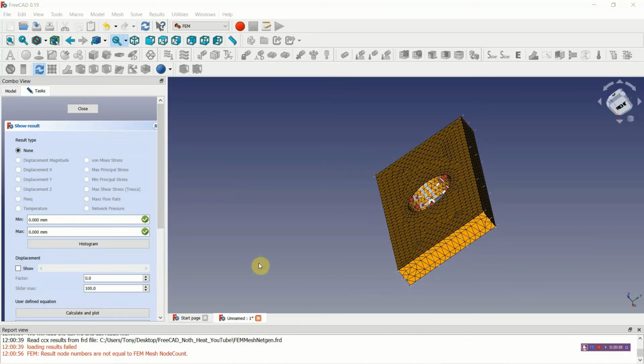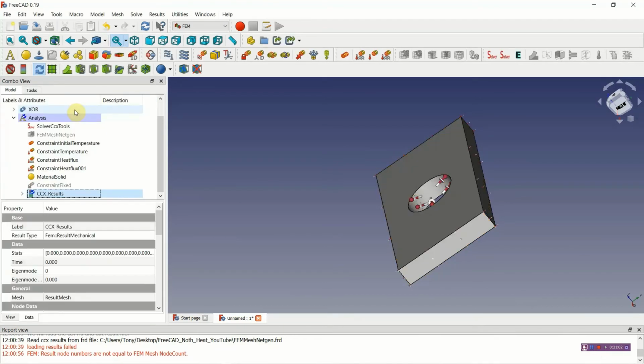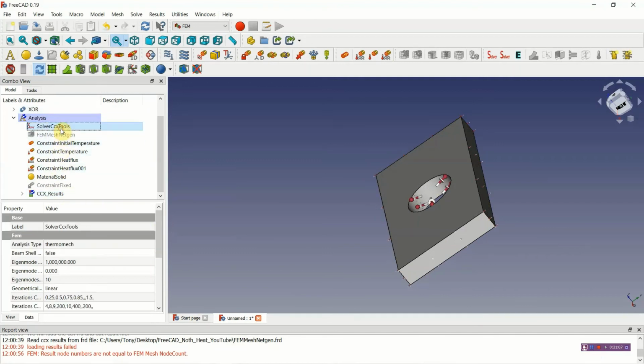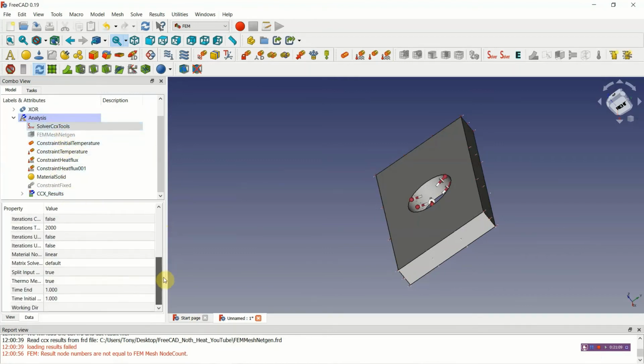And what I'll show now is a transient analysis. So we close this. Now you can change the analysis type in here. I don't tend to like working with this so much. For example, some of the things you can do here, this is this split option for splitting up the data set. And if you wanted the complete data set, you'd put false. And if you want to have these include files and split it up, which is a useful thing to do, I think, you have true.